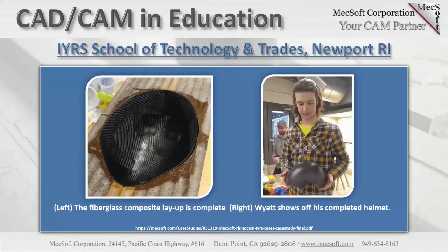Now, one thing else that I want to point out here too, the foam inserts, they use the same cavity mold for machining the foam insert. So they filled it with the foam, and then they machined out, I think it's 10 millimeters thick from the outer shell offset, and then machined that out, and then fitted that foam insert into the helmet.